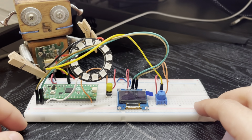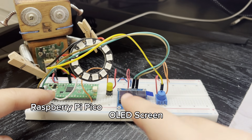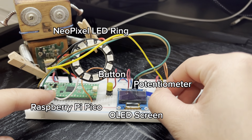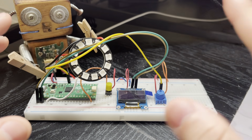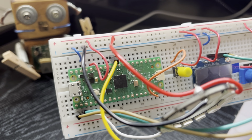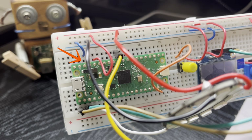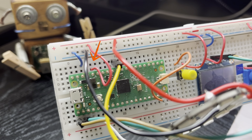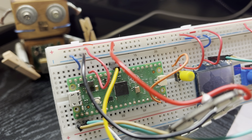So here is what I used for the project: a Raspberry Pi Pico, an OLED screen, a NeoPixel LED ring, a button, and a potentiometer. It might look a little messy now with all the wires, but I'll explain exactly what connects to what and why. On the Raspberry Pi Pico, pin number 38 is the ground, connected to the breadboard ground line, and pin number 36, the 3V3 out, which is 3.3 volt power, is connected to the breadboard voltage line.